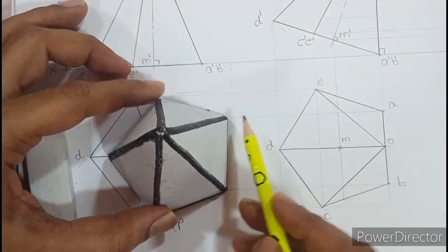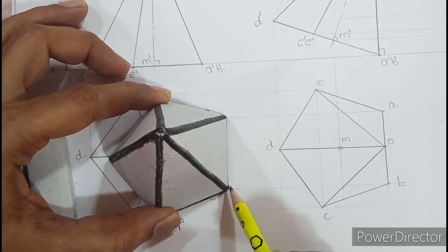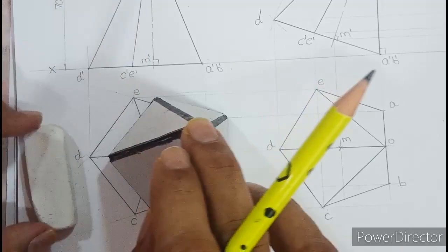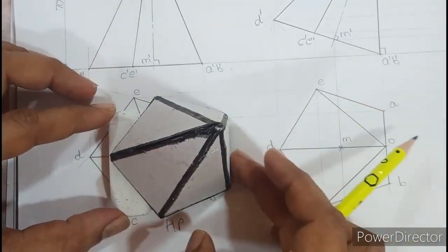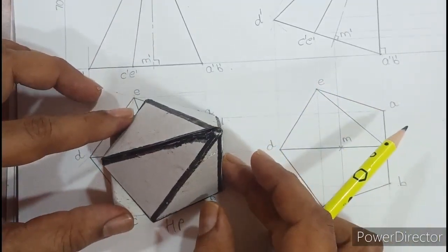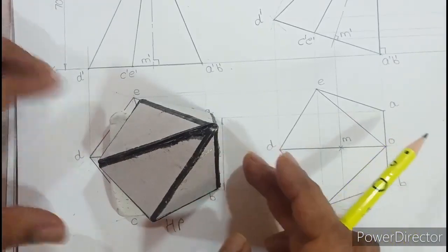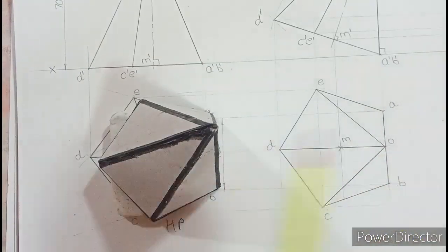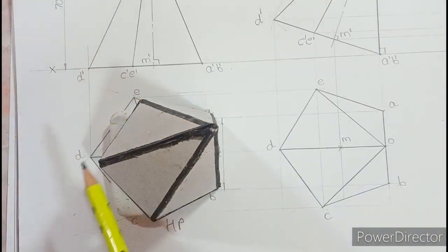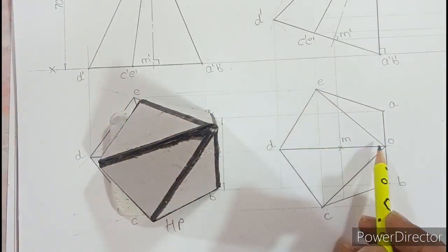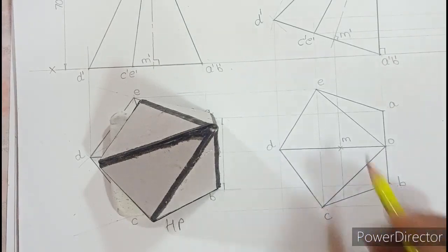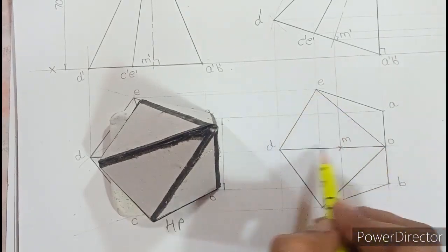See, initially A was here, B was here and O was the apex. You can see them separately as a triangle. But the moment you tilt and try to make that triangular surface perpendicular, AOB will fall in a single straight line. That is what you can see. Apart from that, you can see all the slant edges dark. So that is why all these slant edges have been drawn dark. So there are no hidden lines. By mistake in the exam, what students do is that they draw hidden lines over here.